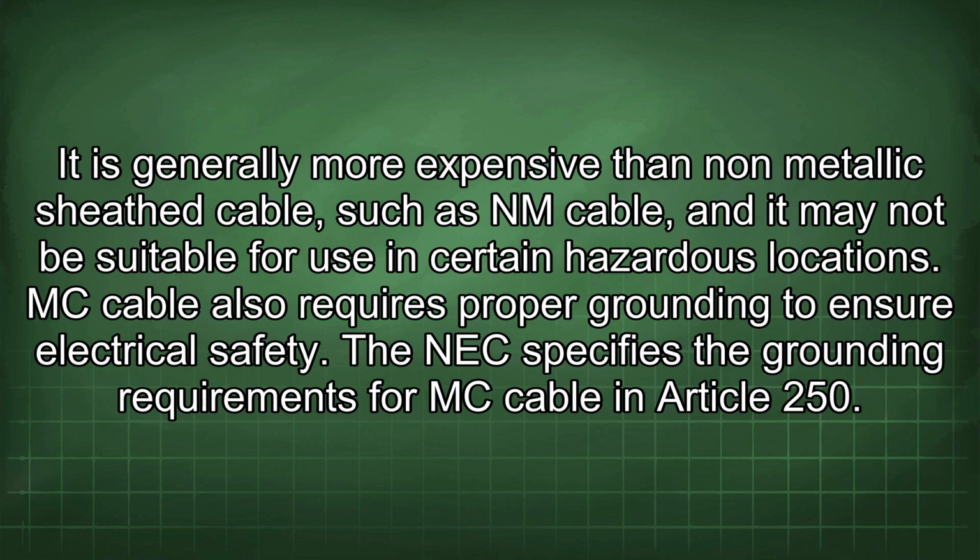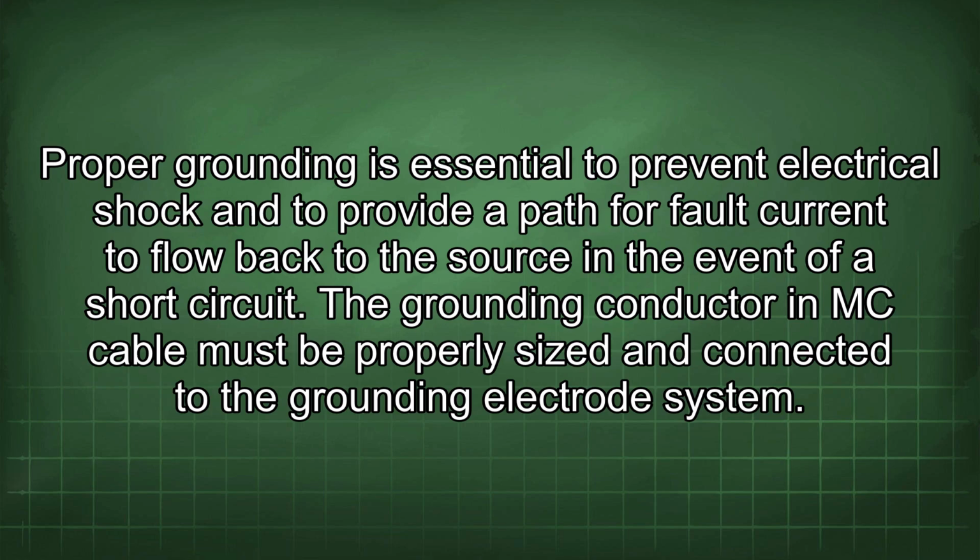The NEC specifies the grounding requirements for MC cable in Article 250. Proper grounding is essential to prevent electrical shock and to provide a path for fault current to flow back to the source in the event of a short circuit.